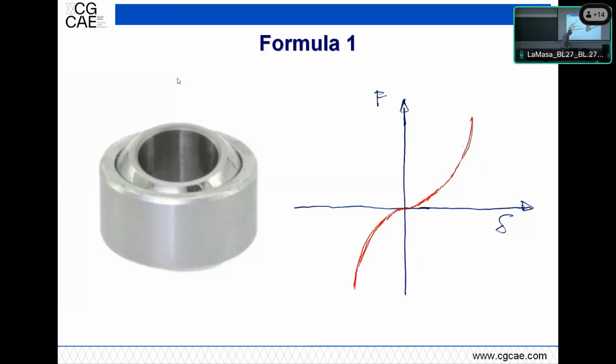So those things clearly need to resist the loads that are coming from vehicle dynamics models, which are compared with the telemetry data, of course. And so the structural group in general gets a set of loads from the vehicle dynamics group or from the track. And the design is done on those, which are in general the envelope of all the tracks, et cetera. So there is already a certain safety in the loads that you get.